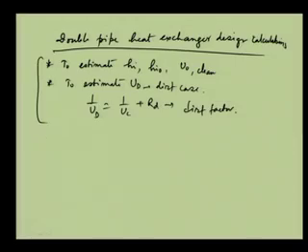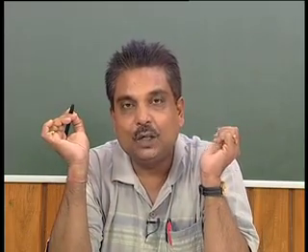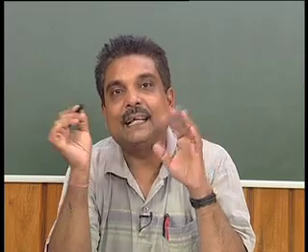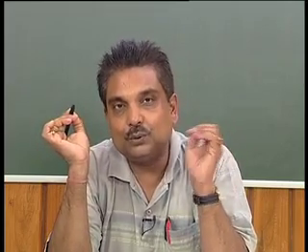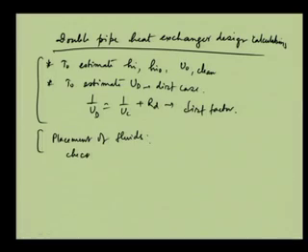And then this is the first thing. Second point is placement of fluids. Where to put which fluid? In the double pipe heat exchanger, there are two flow regions. One is the inner tube region, another is the annulus region. Where should we put which fluid? It depends upon that. We have to check the pressure drop, delta P, and whether delta P is allowed. So, we have to see what is the allowable pressure drop for the two streams.